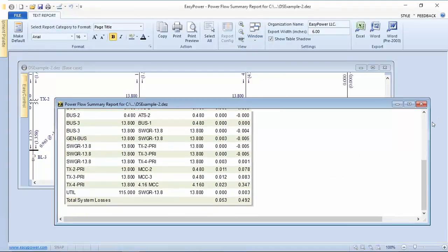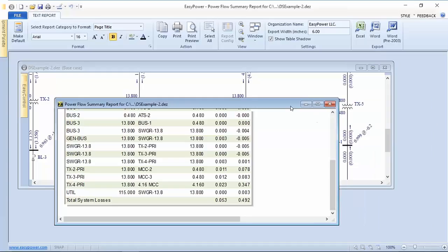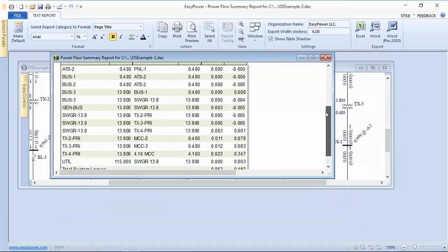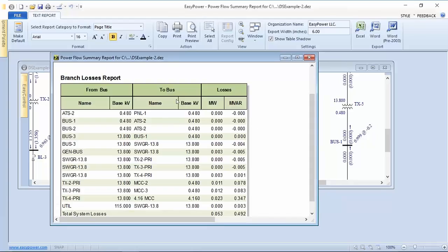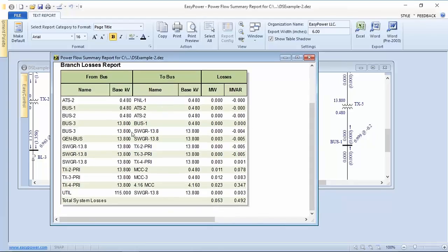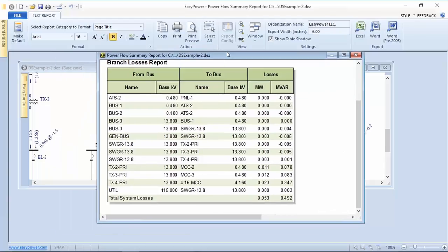So the point being, now we have, based upon the time that we took the readings on the SCADA system, these indicated losses for each of the branches. Now, because this was our first order approximation, our first step, they still aren't necessarily exactly our actual physical system. There still could be some errors, and we want to take steps to do a bus-by-bus comparison to make sure we're not missing anything.